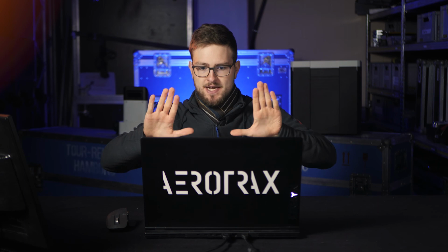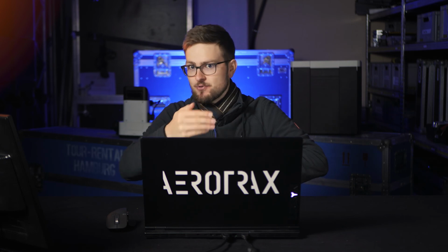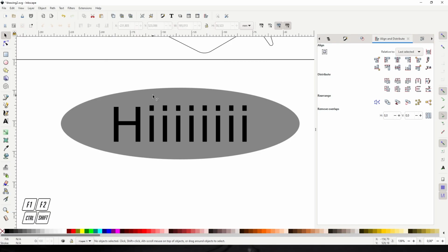What I want to do is recess that text in a special way. So I want to have the flat surface of my wooden board. Then I want the gray ellipse to be recessed, and I want the text to not be recessed, so it has the same height and is coplanar with the rest of my wooden board. The thing is, if I just export it like this, and of course I would convert the text to a path first, Shaper Origin still sees the ellipse and the text as two individual shapes or groups of shapes. And it doesn't recognize, while you're pocketing that ellipse, that there's a text it's not supposed to hit with a milling bit.